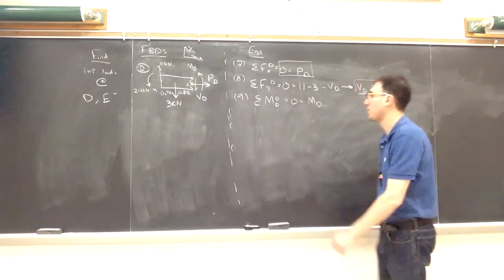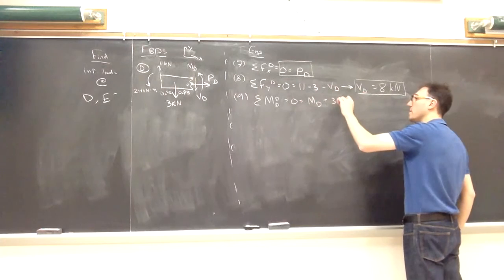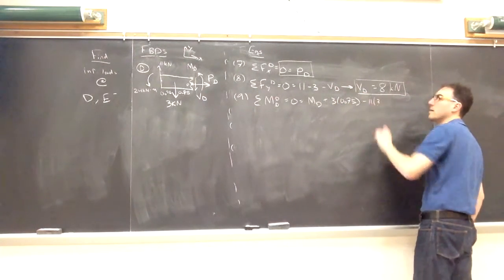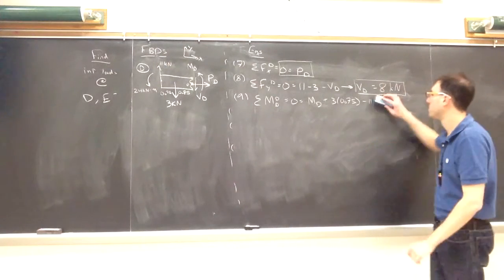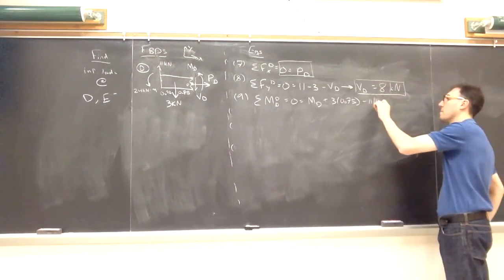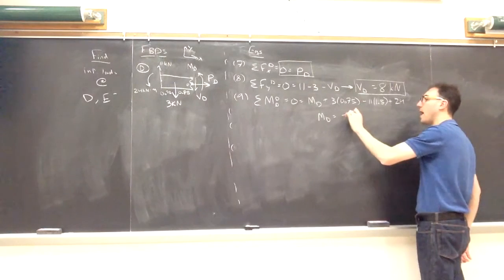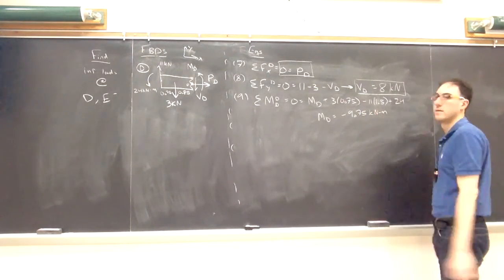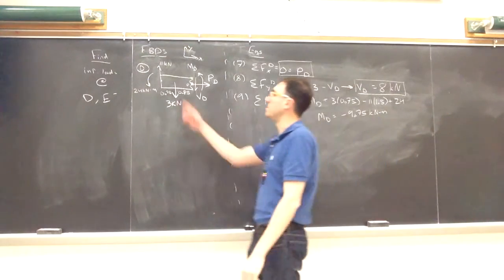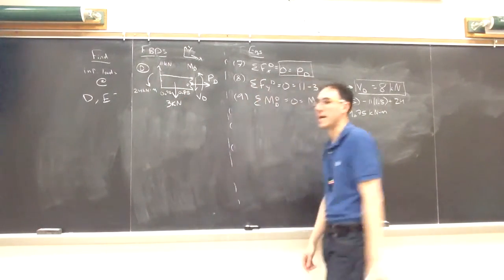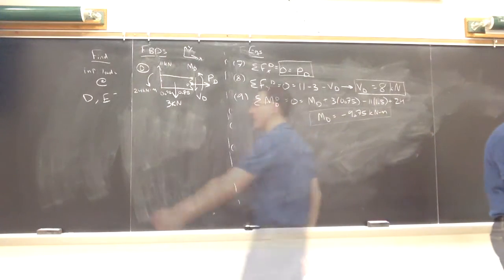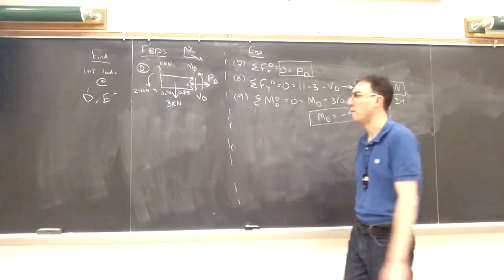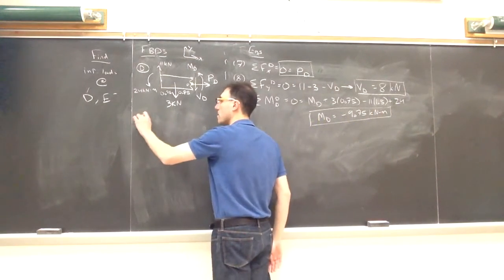I have to include that 3 times 0.75 minus 11 times 1.5. Negative 9.75 kilonewton meters. Yep, so we have 2 forces and we have that couple at the edge. D then is taken care of. So we need to look at what's happening just to the left of point E as our other picture.